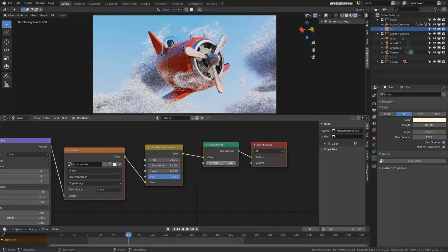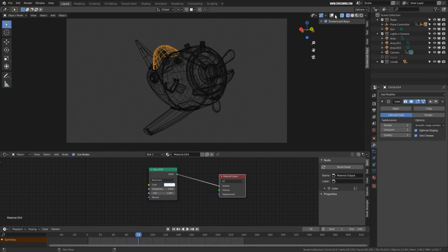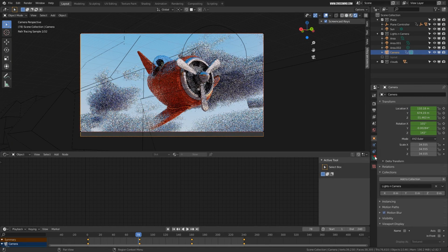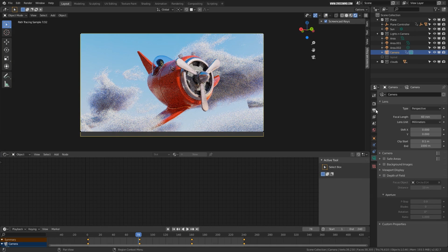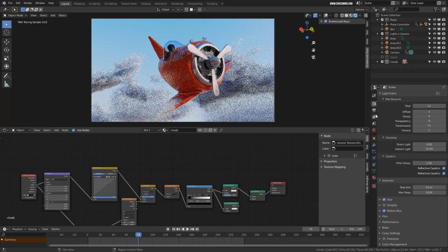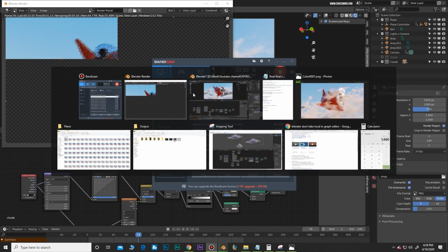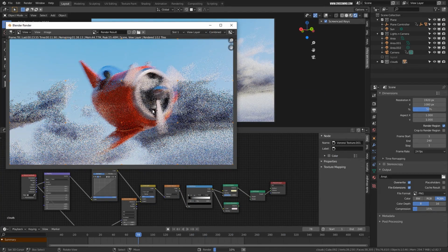And now before we start rendering this, the first thing, I'll apply some camera effects. Let's select the camera, enable the render, and disable the depth of field which we had created earlier. Go to the render properties and enable the motion blur. Now to view the motion blur, first let's just make the render size smaller from the render output properties and render image. Now you'll see there is this motion blur in the entire image.